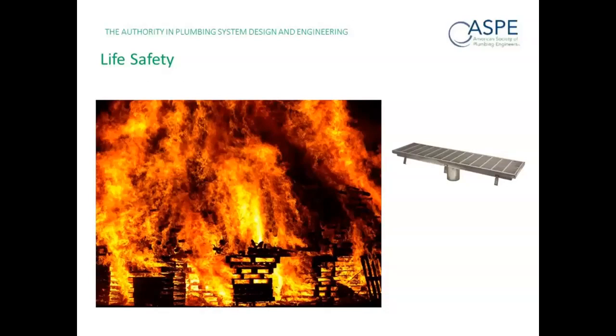Stainless steel has all the best fire safety characteristics and is really the preferred drainage on board cruise ships, where safe evacuation of passengers is critical. The same consideration goes into the hospital environment. It is important to note that stainless is non-combustible and as such is exempt from the ASTM E84 and UL 723 tests for surface burning characteristics of building materials. It does not produce smoke or gases from paint or additives, and doesn't produce any burning droplets to spread the fire downwards in the building. And additionally,